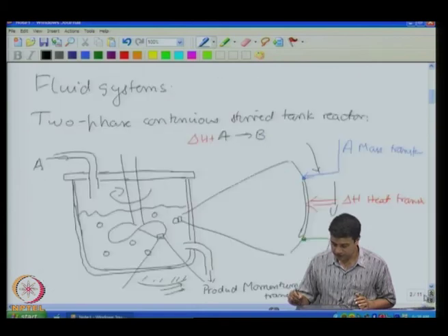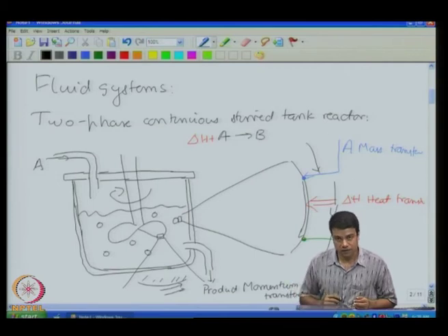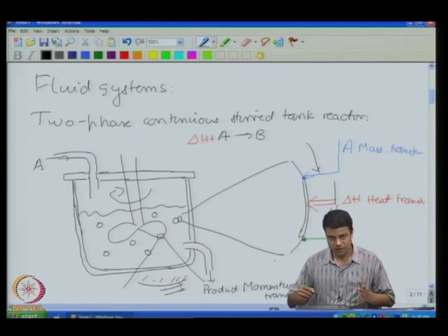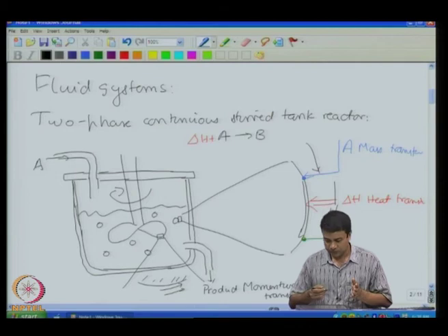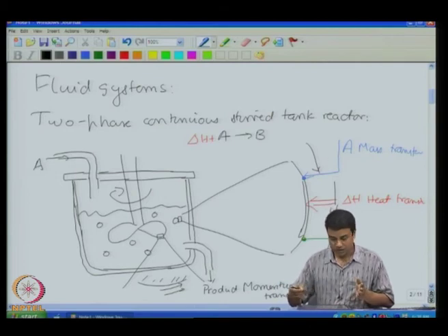For example, if we take this reactor example, convection can transport material from the inlet to the fluid surrounding this catalyst particle. However, there is no fluid velocity perpendicular to the catalyst surface, because the fluid cannot penetrate the surface. That means that the motion to the catalyst surface, which has to occur in a direction perpendicular to the surface, can take place only due to diffusion.